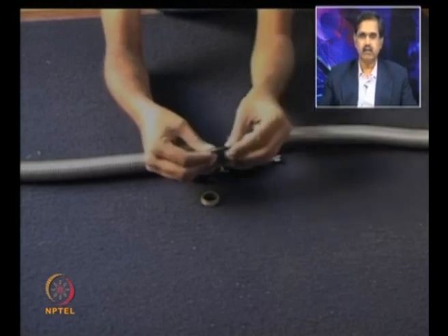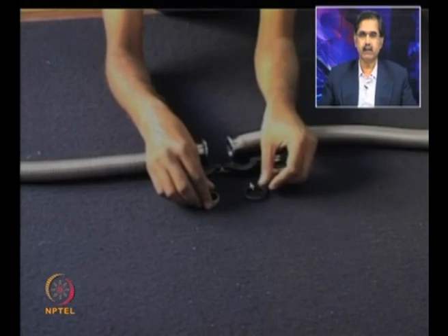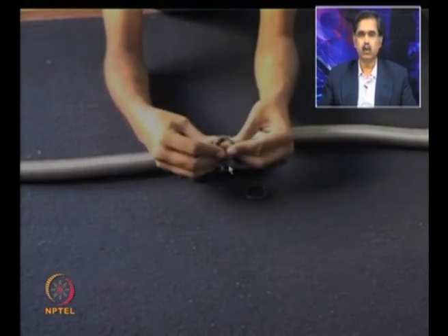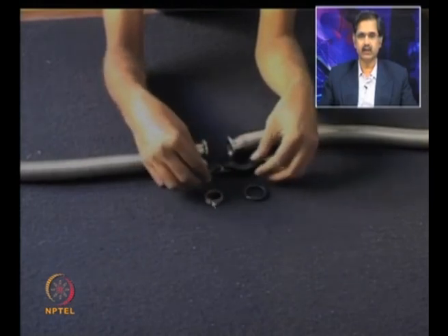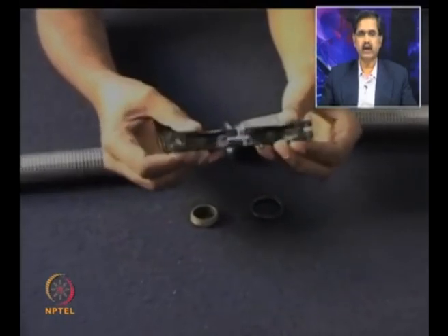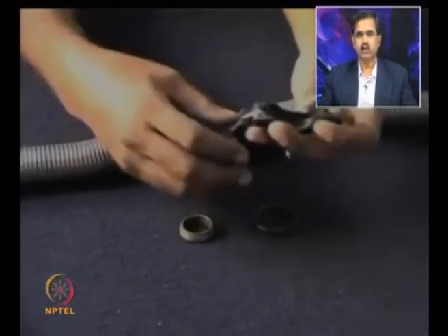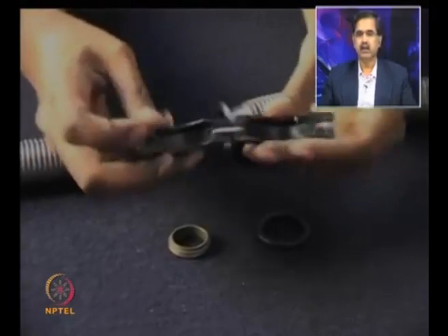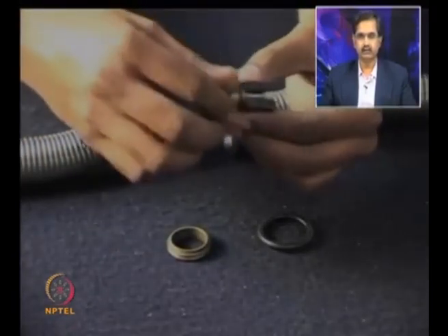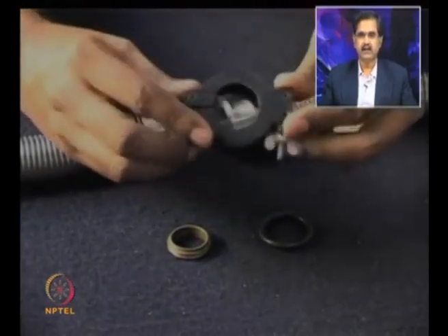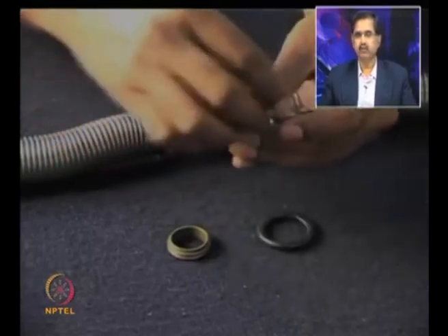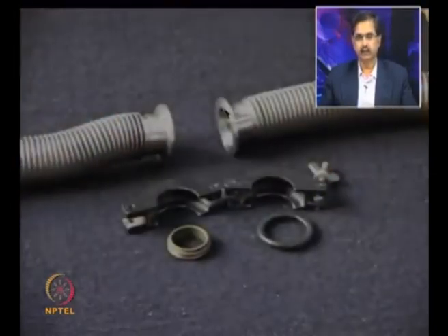It has some kind of sealing in between. You can see some rubber sealing, and a brass ring on which this rubber sealing sits and stays. So, there is a kind of housing over here, and then you have a coupling. This is what constitutes a KF coupling, which is normally used in connecting these vacuum hoses, made of stainless steel, and you can see some corrugation here. This is the way the coupling is assembled together. You have a nut at the end which actually puts them together.